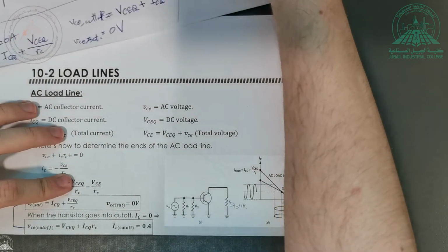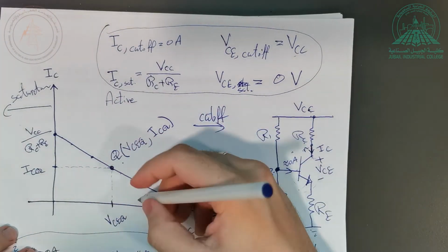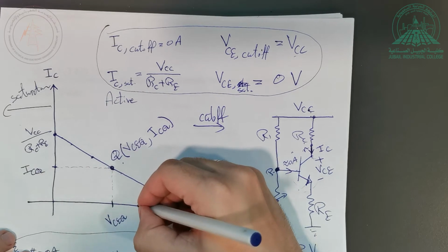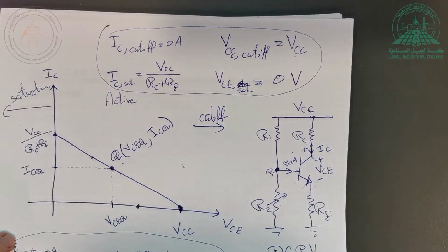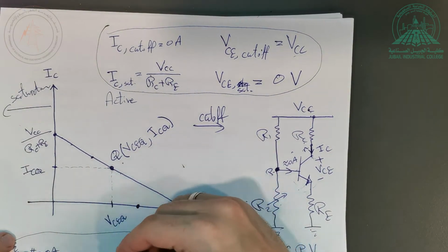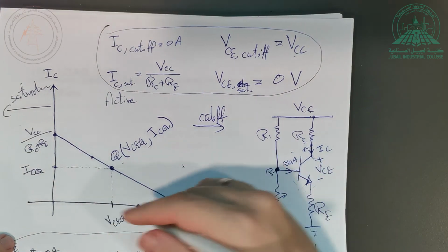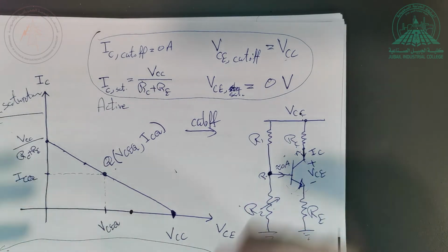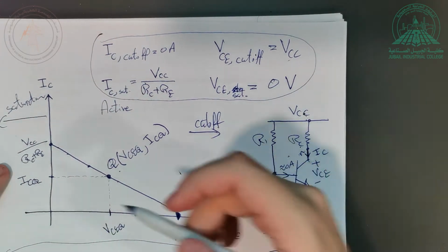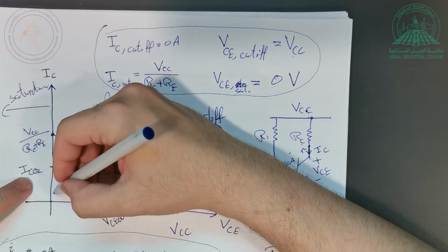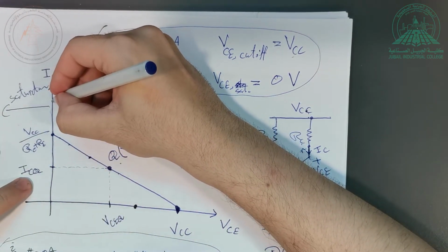So usually, if we draw it, usually I see VC. If you do that, usually this point will be here, which is VCE cutoff. The VCE cutoff for AC is going to be somewhere here. So it will be below VCC, of course. Nothing can go beyond the VCC because this is your DC supply. Okay, how about the IC? IC actually is going to exceed that, so it will go up. It will be somewhere here like this.